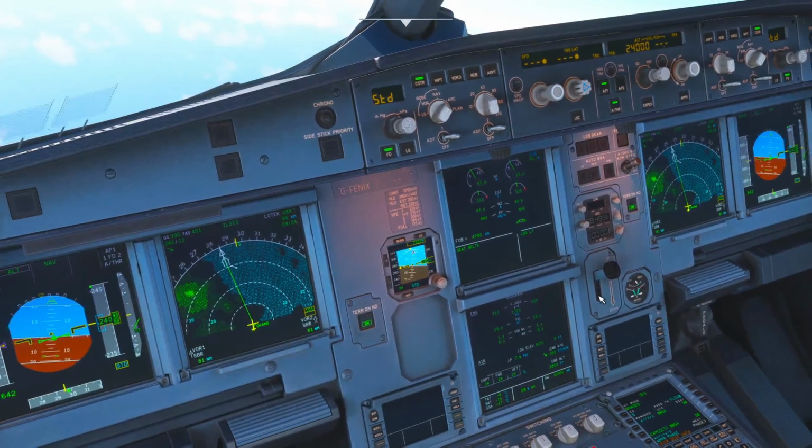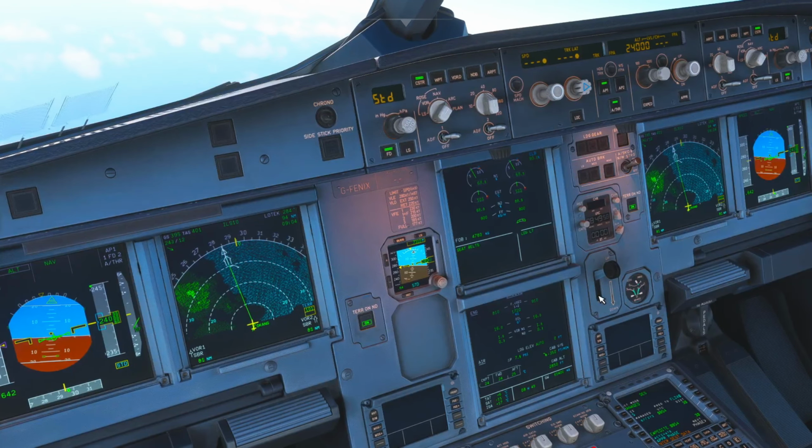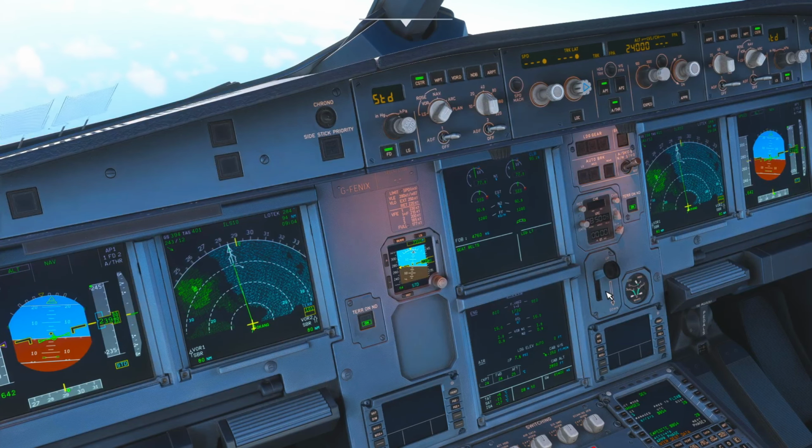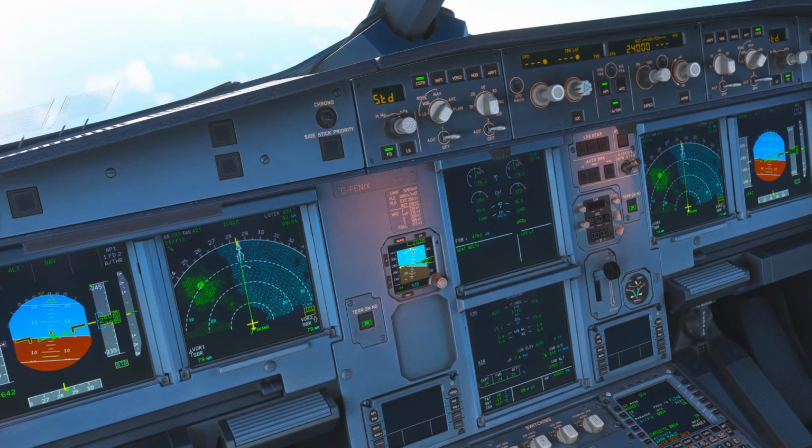And for ILS or CAT 3 autoland, where the localizer and glide slope modes are both engaged and the runway is usable for automatic landing, you can let the autopilot land the aircraft for you in an autoland.